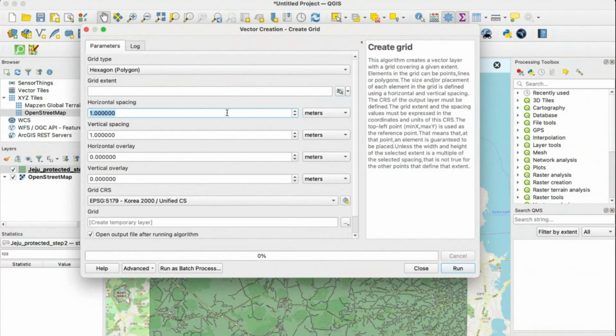We need a certain amount of gap between wind turbines. Usually, that is going to be 5D, which is 5 times the diameter, or if the wind turbine is big, then it becomes 8 times the diameter, so that the turbulence of one wind turbine does not affect the mechanical structure of the next wind turbine. So basically, to avoid any mechanical failure, we need a certain amount of gap.